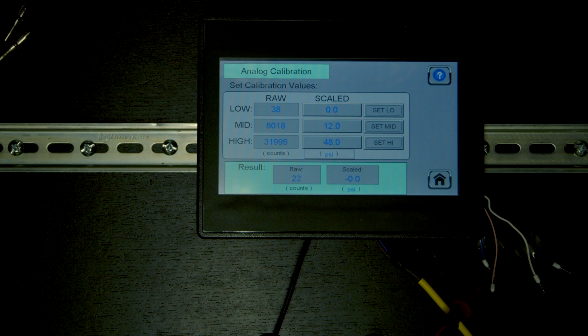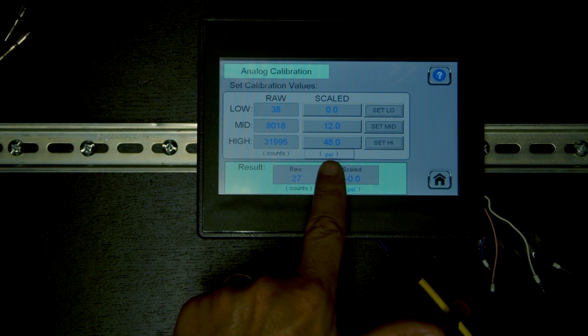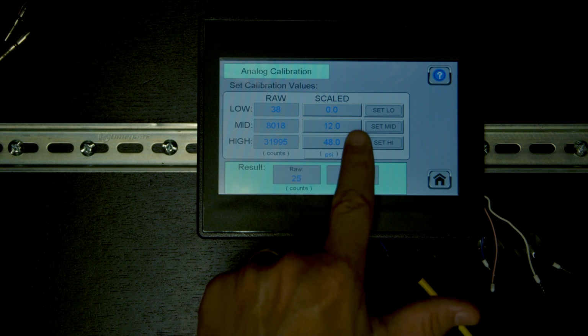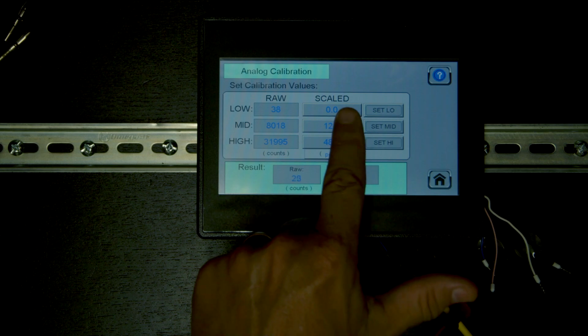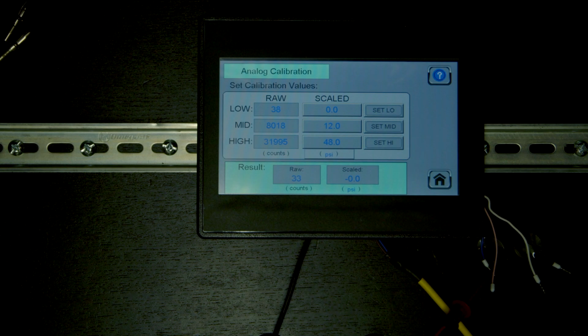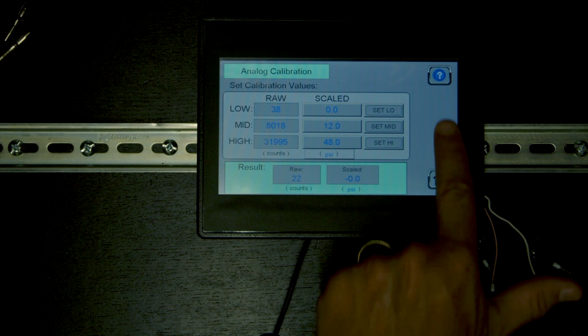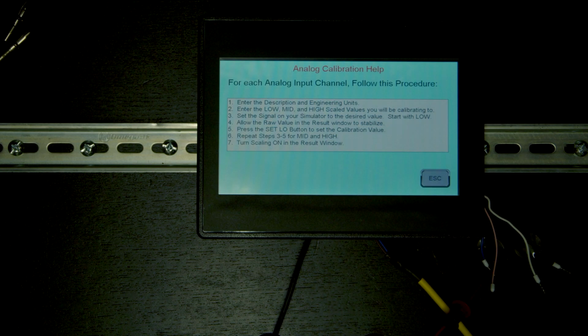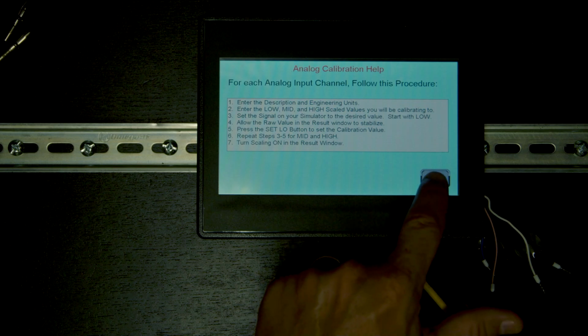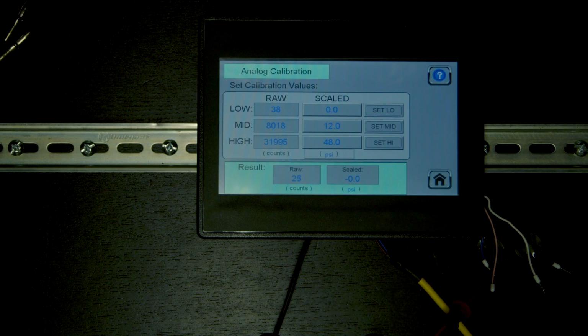And the instrument we need for this is an instrument that's going to measure accurately, that we can trust, a traceable instrument, that in this case is going to measure PSI. So what we're going to do is set the machine to these 3 different PSI levels, verify it with this third-party instrument, and then once we're happy that we're at those levels, we're going to go ahead and perform the calibration. Now, the detailed instructions are also available with this help button here. But I'm going to walk you through it, so we aren't going to study those in detail here.